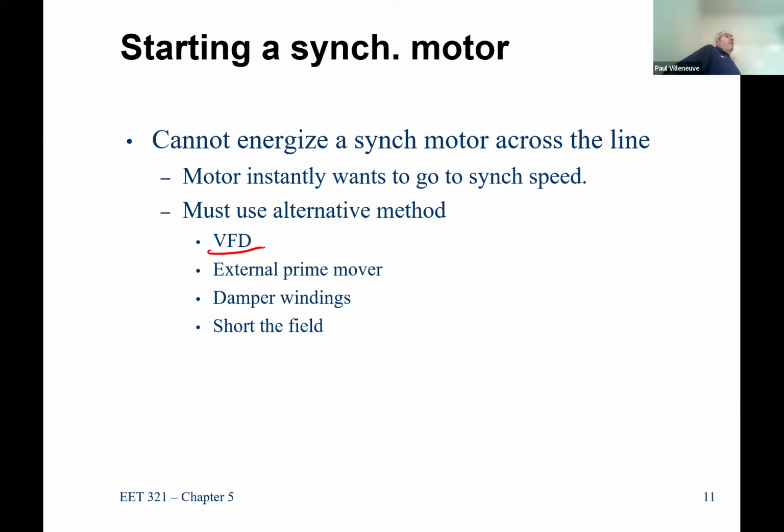And then once you get it up to 30 RPM, then you take it to 60 and 100, and then you ramp it up slowly so that when you get close to its nominal synchronous speed, then you can go ahead and light off the gas, and then you can get it to rotate. So that's how GE does their 7FA ones, their gas turbines. An external prime mover, why not just take a motor on the output and actually get it to rotate and start it that way? So you know that